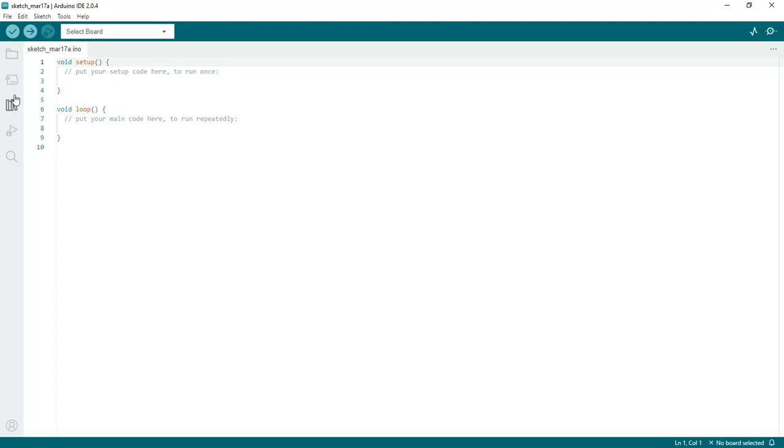The Arduino IDE working is very simple, and it has these two parts. Every program is going to maintain these two sections compulsorily. This is the configuration of your application, which is called the setup part of the Arduino. Setup always maintains what inputs you are connecting with the Arduino board and what outputs you are connecting with the Arduino board. All these you need to configure here, using pinMode, which is a macro. This pinMode macro you need to use in the setup configuration for input or output purposes. So that is your setup part.